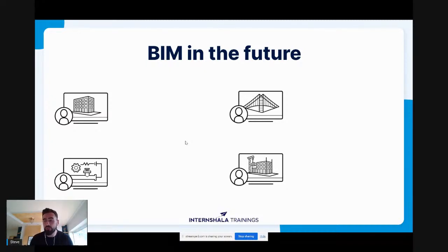So as well as the BIM for the modeling, we also have what are called building information modeling objects, or BIM objects. So these are the components of the building. So BIM objects are the components that contribute to the model, for example, a door. So when elements are changed, the software will update the model to reflect the change throughout. So this keeps everything coordinated through the process and shows how it will impact cost, timelines, and other resulting changes.